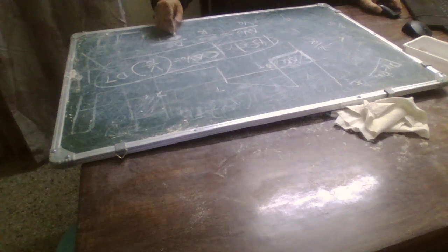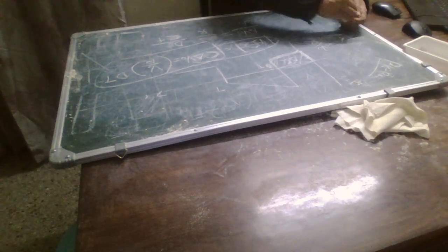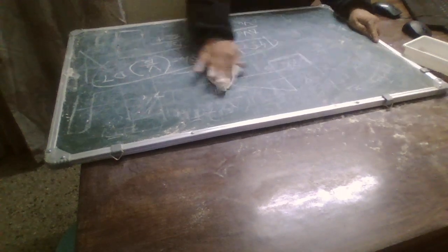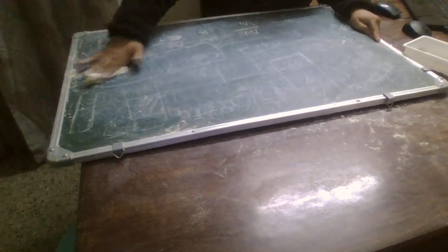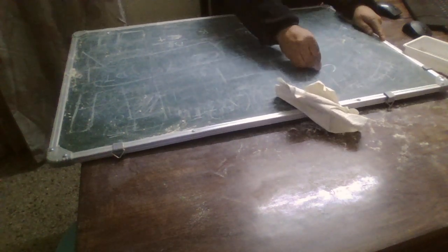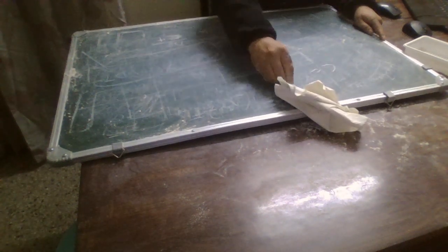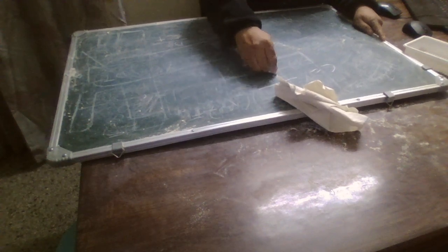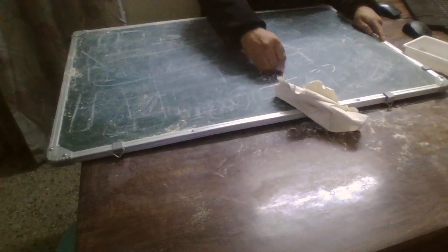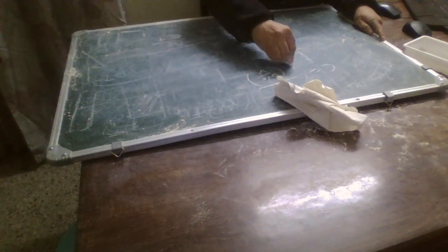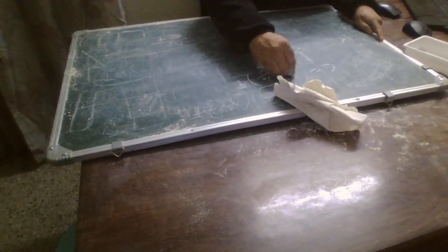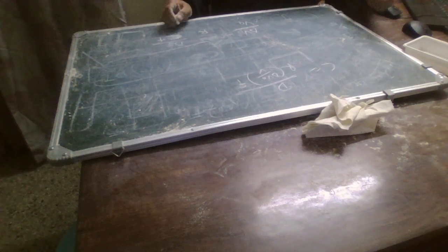If I rearrange it, I will get C equal to D upon delta V naught upon V naught, R and the switching frequency. So this much should be the minimum capacitance for this ripple voltage.